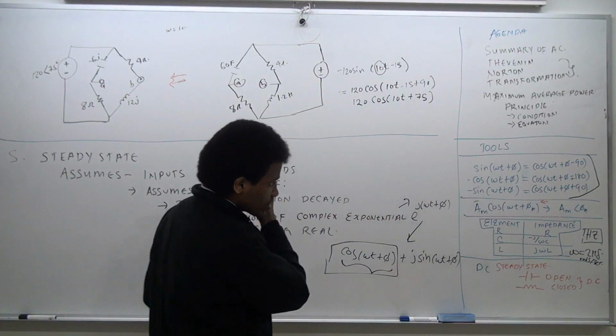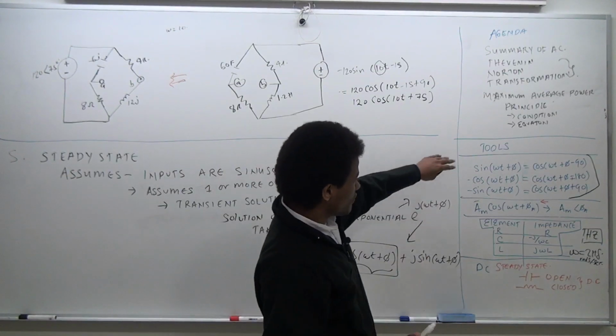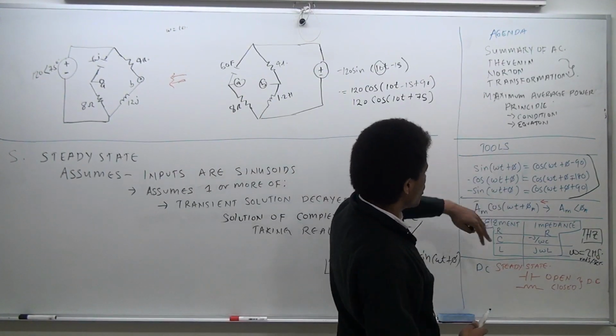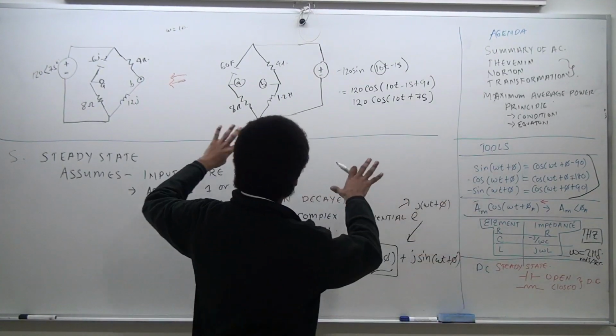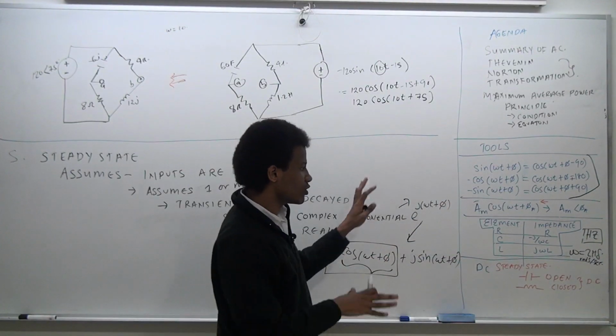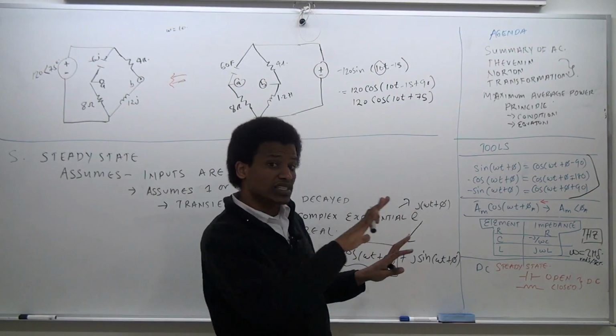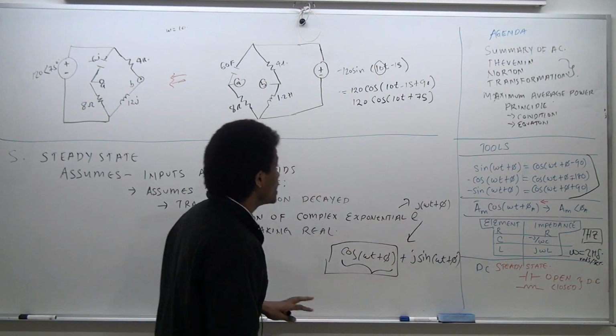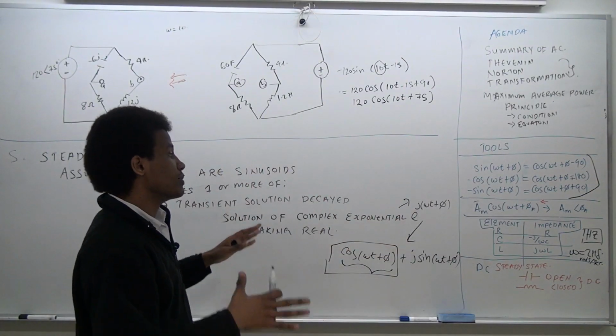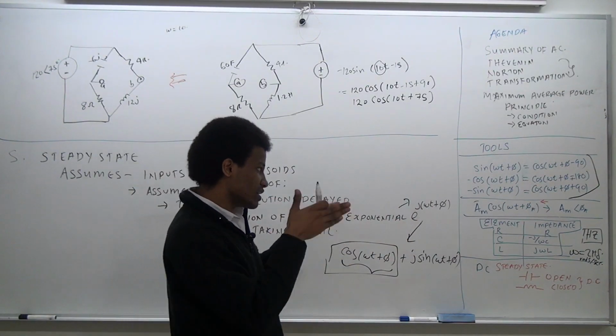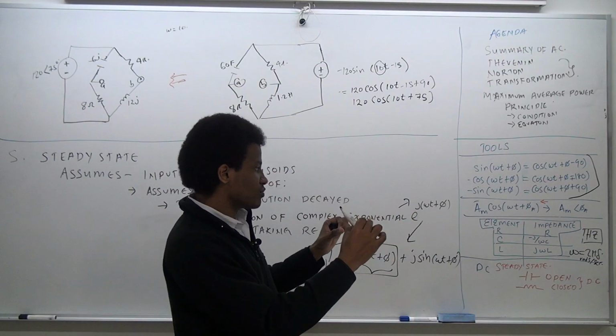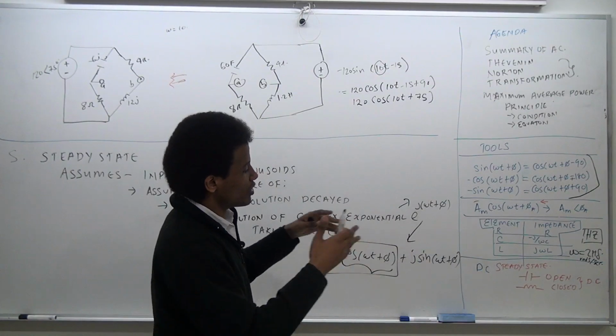Another thing is when I previously talked about if, let's say, you had multiple frequencies, how would you deal with that? You would deal with them exactly how you would normally deal with single frequencies, but the only difference is you would consider every single frequency individually and sum up the response at a specific reference point that you're considering in the circuit, and just add up all the responses individually.